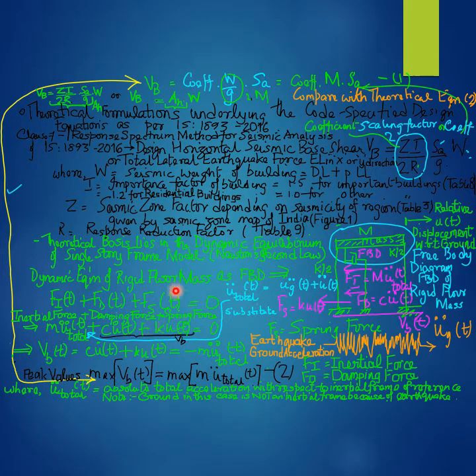And the sum of three dynamic quantities, that is the dynamic inertial force, the dynamic damping force, and the dynamic spring force, all three expressed as functions of time, or time variant functions, should equal 0 for the free body to be in dynamic equilibrium. The prefix dynamic signifies that the equilibrium being considered is the equilibrium for the motion of the floor mass.